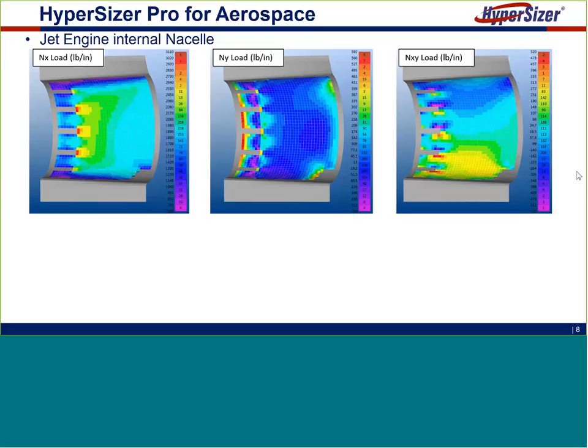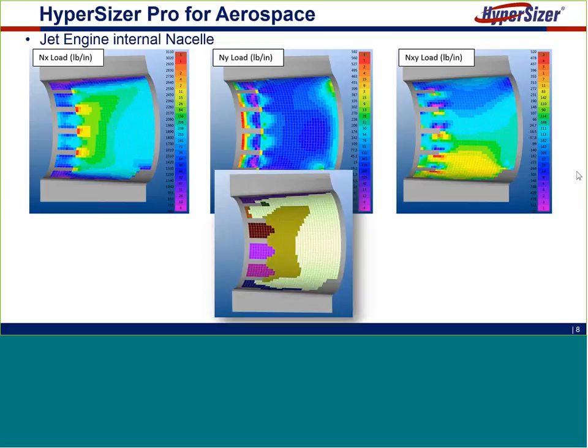But one should also consider the bending moments MX, MY, and MXY, and the out-of-plane shear forces QX and QY. Then there's the issue of hundreds or literally thousands of load cases. And you can see it becomes intractable to manually establish optimum property zone patterns. So this was the beginning of the Express product to address this need for the larger composites market. And the last image here is a representation of one of the attempts of defining what finite elements should belong to the same property card.